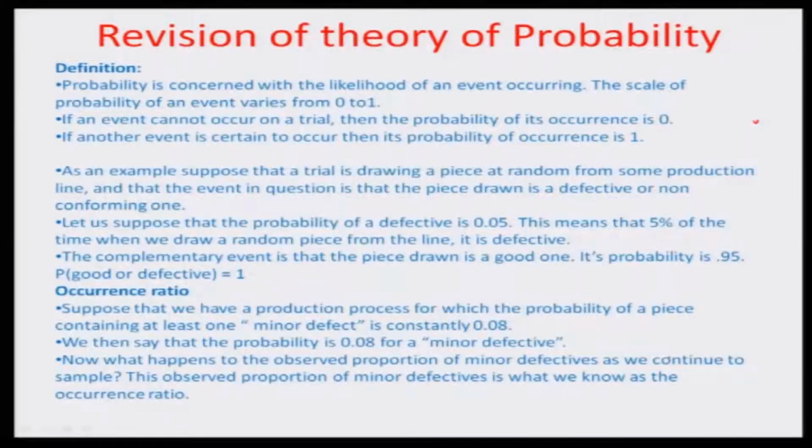So that is all that I have about the X bar and the R charts, which are one of the big references in the industry for studying the process control. We will now go to another aspect of control charts, which is about the fraction defectives. So there are certain parameters of quality which cannot be gauged by a particular unit or a value or a dimension or a quantity, and in this case for example let us say how a product looks visually is never quantifiable with any measure. So there can be some kind of acceptance sampling in that case where we are talking about either a complete elimination by looking at a product which does not suffice to the quality characteristics, or accepting a product based on the perception of the customer, okay.